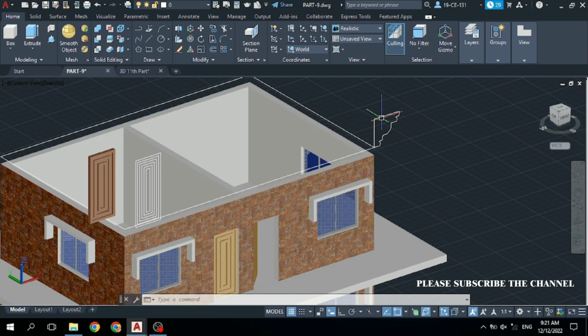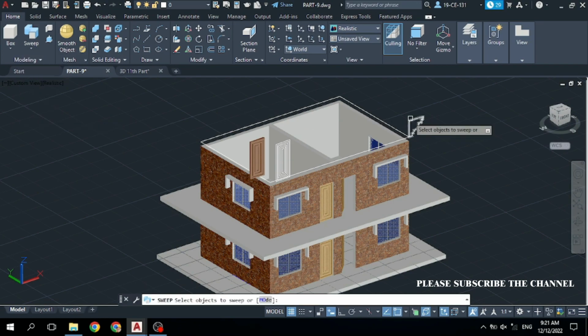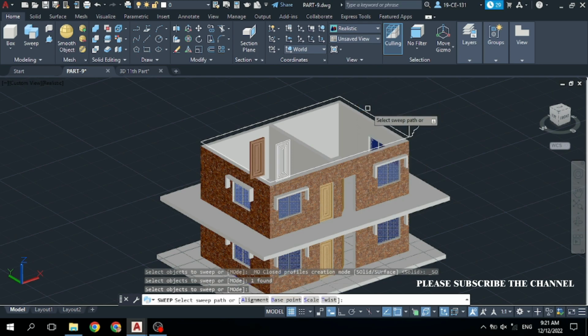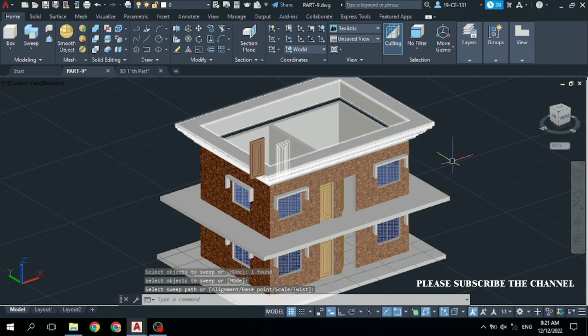After that, create this 2D object. You can see this 2D object by the help of line command and arc command. And if you cannot create it, I have given its video link in the description, and go there and watch that video on how to create this 2D object. So it is easy. And after that, click on sweep command and select this 2D object and press enter, and then select this rectangle. Now you can see it has created the roof.